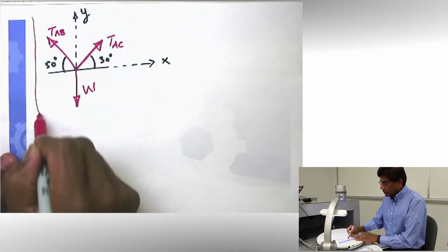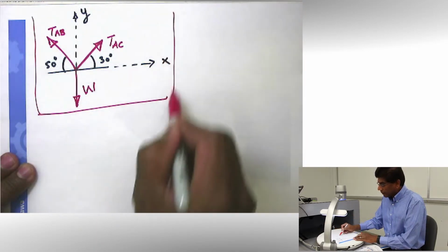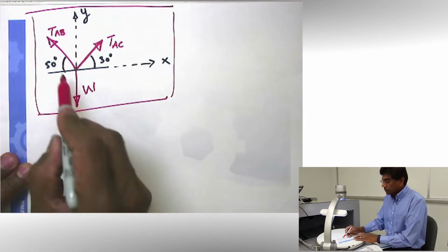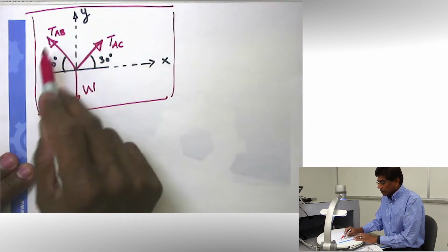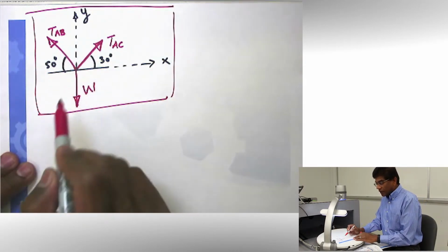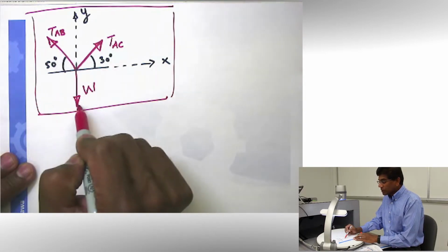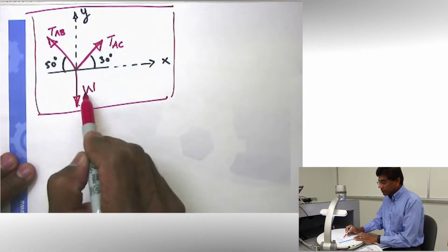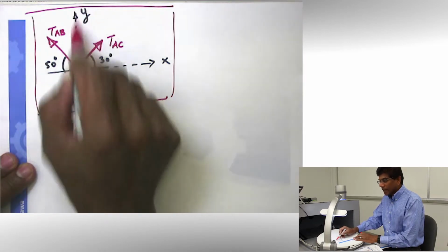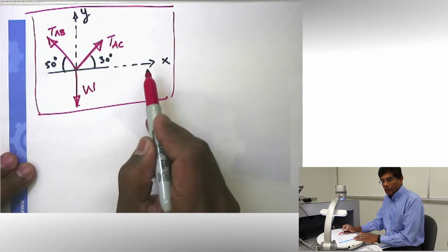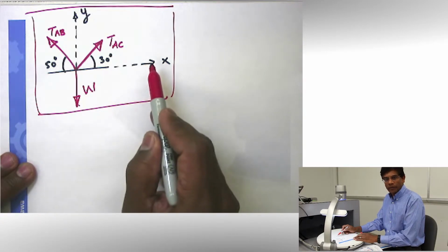Again, steps in drawing free body diagram. Isolate the area of interest, draw a sketch, show all the forces, label all the forces, show all critical information, attach a coordinate system. You will be able to download a handout from the website showing all the steps.